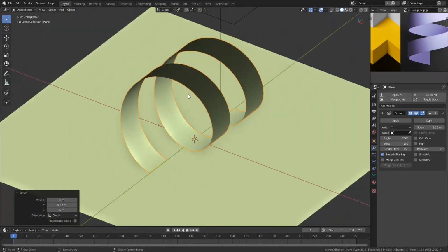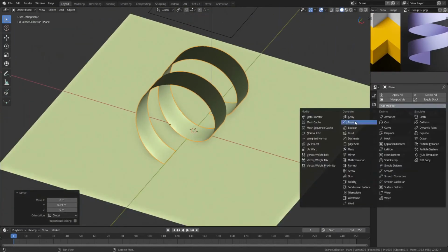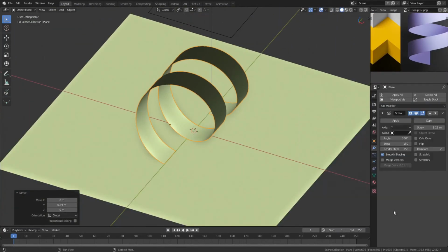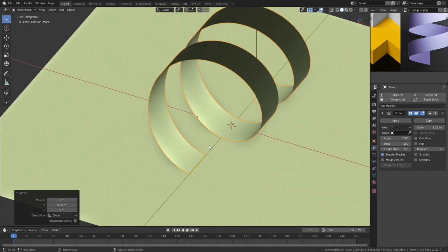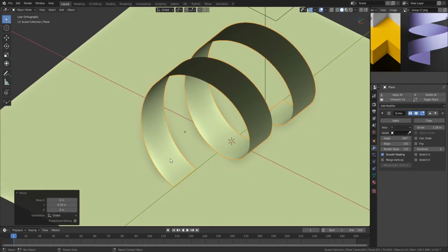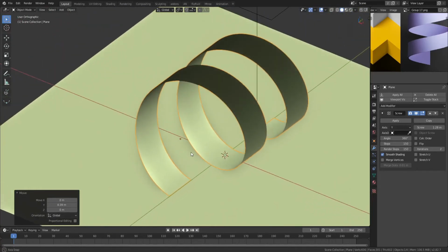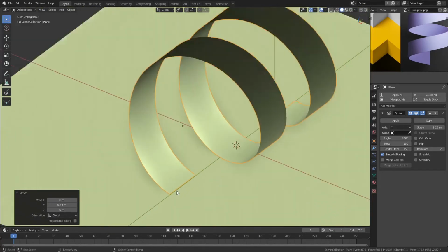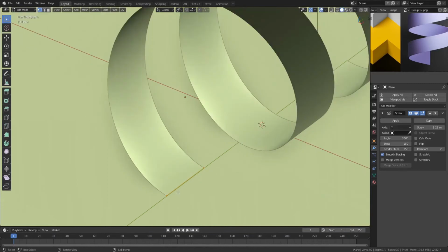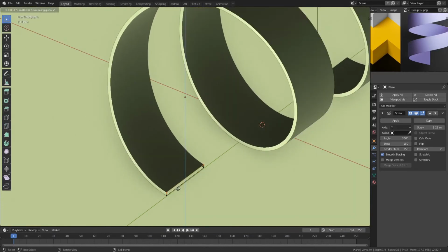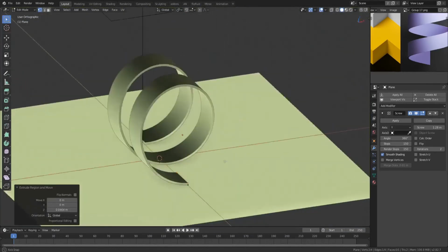And to do that, I will use another modifier. And this is the power of the modifiers, which, by the way, they work the same way in 3ds Max. I know that Maya doesn't have modifiers, but in this case it's very useful for this type of things, because there are many ways in which I can obtain some depth. So I can simply enter edit mode and extrude, just as before. And as you can see now, I have some depth.